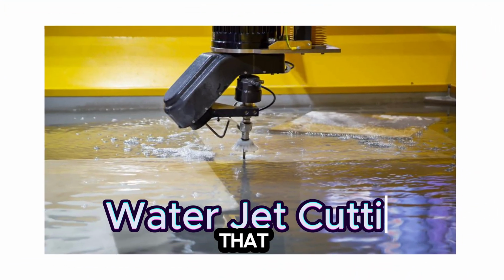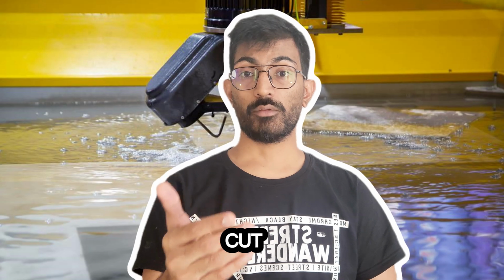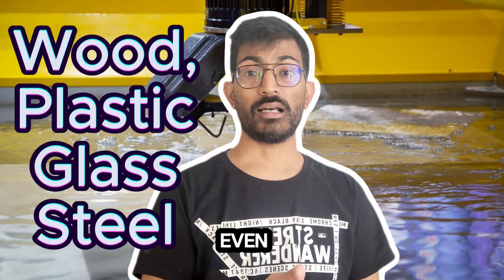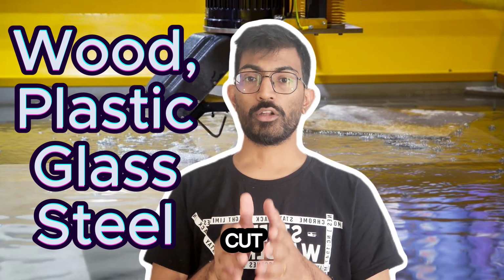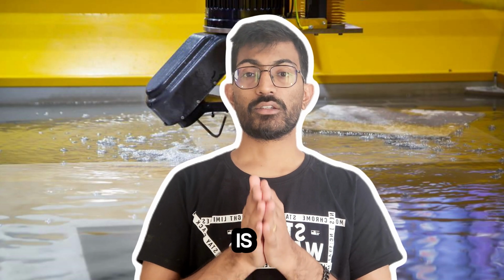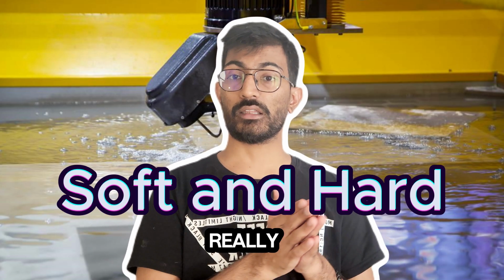Now let's move on to the waterjet cutting. Waterjet cutting is a really good tool if you want to cut a really thick sheet metal. For example, if you want to cut something that is 200 mil thick, or even if you want to cut things like wood, plastic, glass, or sometimes even tiles and stones, you can cut all those using the waterjet cutter. So the advantage of waterjet cutting is you can have a really versatile material. You can also cut a soft metal on this, and you can also cut a really thick metal and really hard metal using the waterjet.